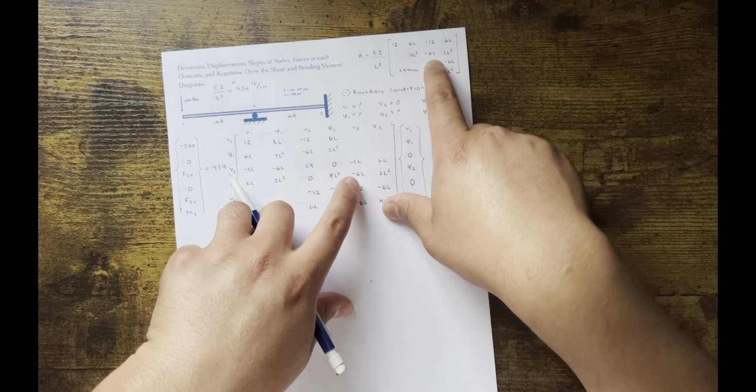But now you go for step number 3. And equations. These are systems of equations, right? For displacements and nodes, or rotations. Let me go put rotations. Okay, so you do that, right? First one, you start with the ones you don't know, V1, Phi1, and Phi2.